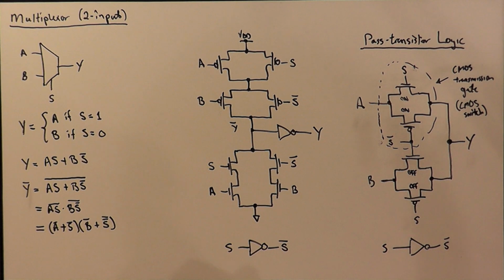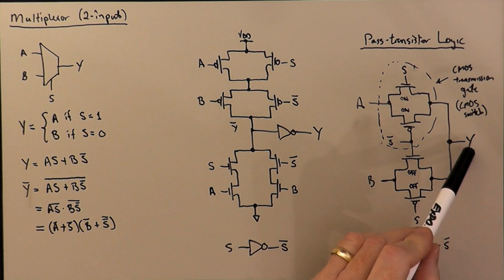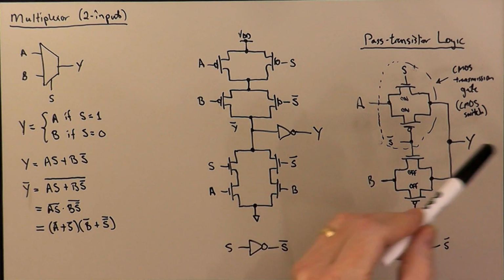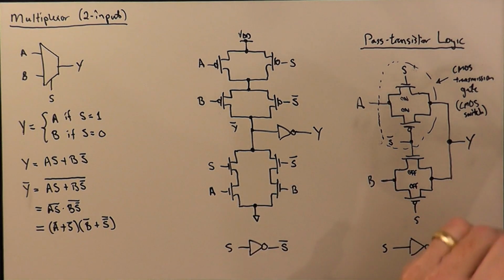If we're using it as a digital multiplexer, sometimes we might put a double inverter buffer on the outside so that whatever's driving A and B doesn't have to drive whatever is coming after this. But there's a very efficient way of making things like multiplexers. You can make trees of these things and basically have an 8-to-1 or a 16-to-1 multiplexer fairly easily.